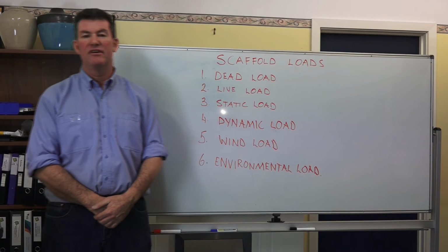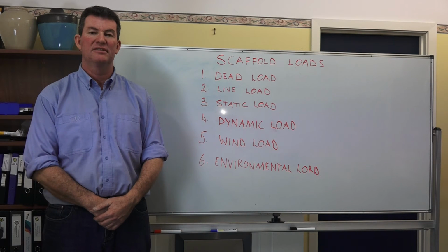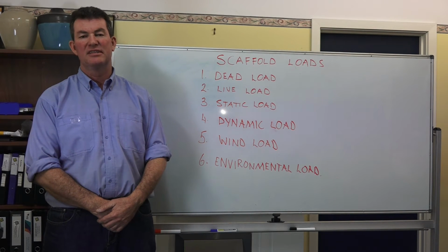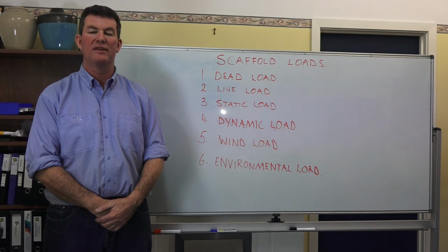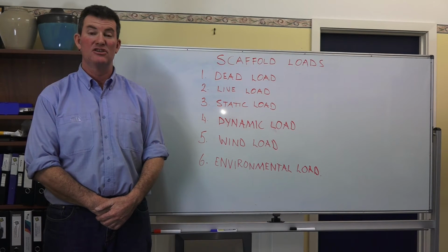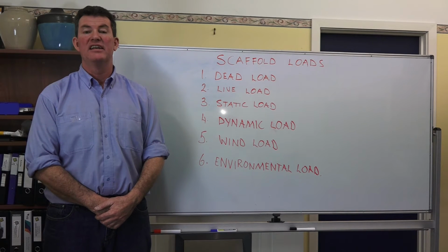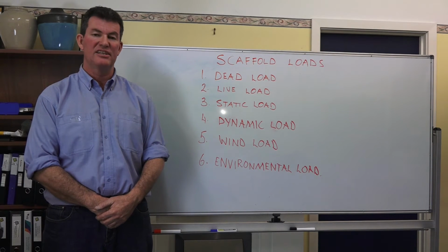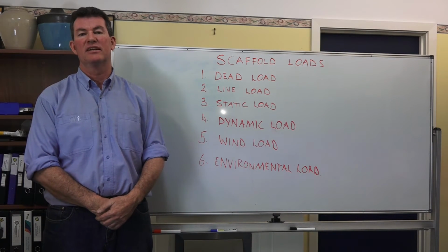Scaffolders need to be aware of various forces and loads that are applied to the scaffold. First load is the dead load. The dead load is the weight of the components attached to a standard being transferred down to the ground. That's not the total weight of the scaffold, it's the part weight of the components attached to a standard being transferred down to the ground.